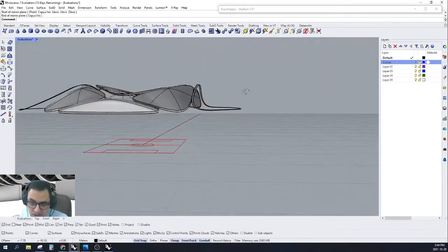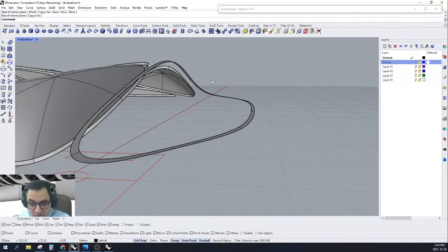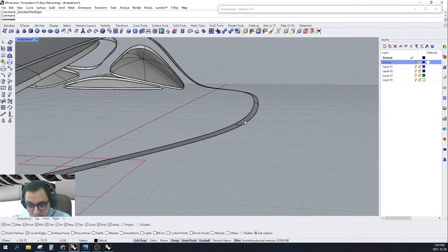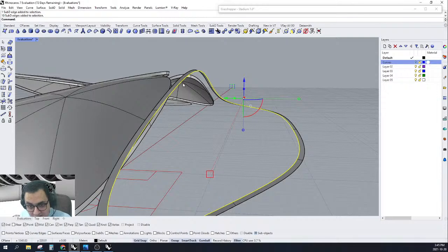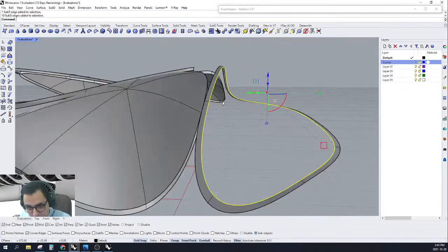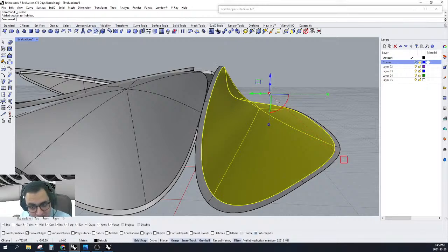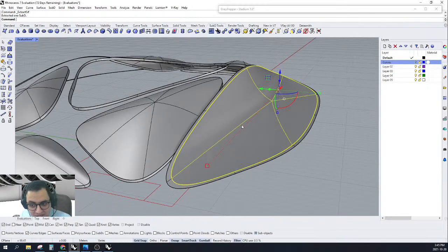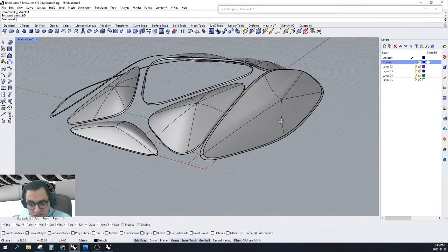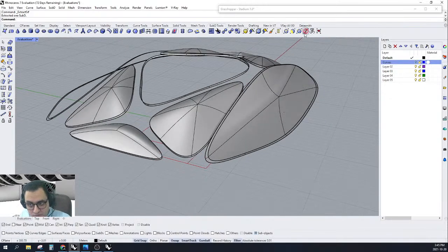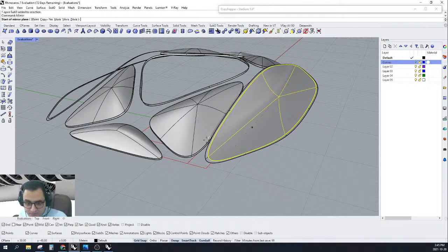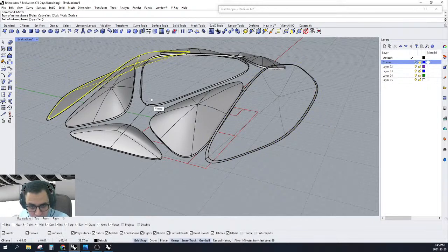Okay, and I will do the same thing in here, but in here it will be a little bit tricky. We can select the inside because it will look weird if we selected the outside. And again, fill subd hole, automatic, add crease and extract. After extraction, we can show, maybe mirror before we show.